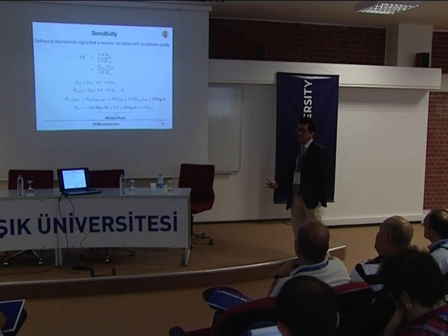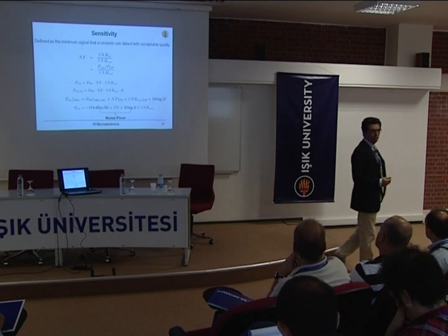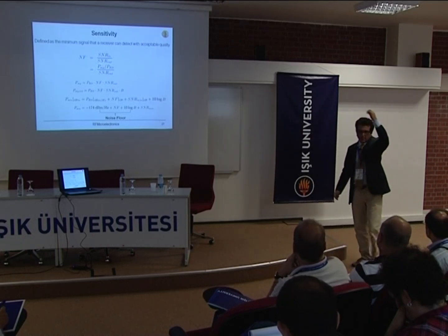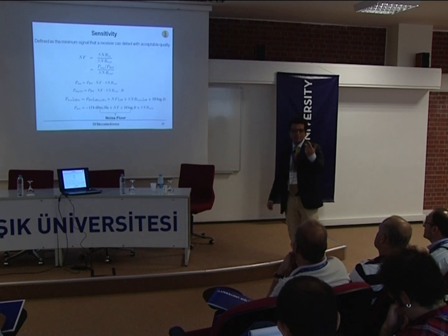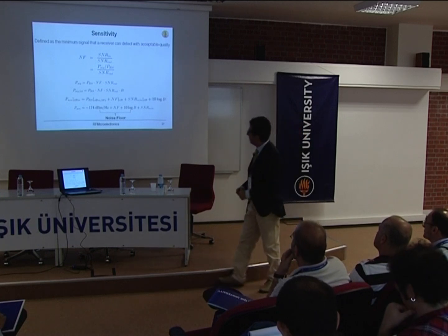For example, GSM, which has a low rate, will probably have a sensitivity much lower than wireless LAN or any wideband application, because the bandwidth increases, and immediately for the same noise figure, the sensitivity figure increases. But that's only an apparent disadvantage.